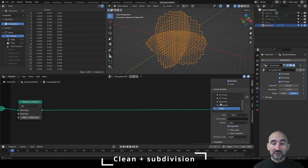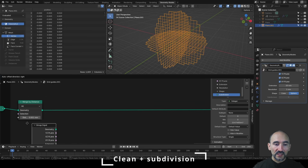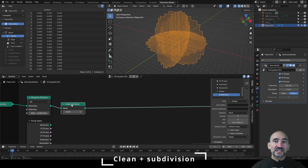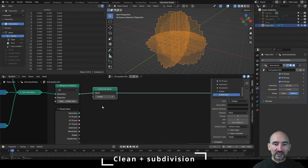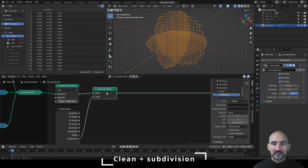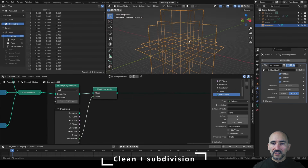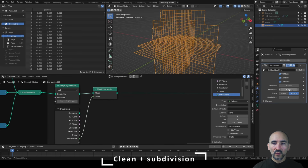Now we can add the other features, so the subdivision. We need to add another input parameter as an integer, and this is the subdivision from 0, and this is a single structure type, and we can add another group input here and add a subdivision mesh, not surface, because we don't want to smooth the surface but easily subdivide each face by 4 for each level of subdivision, and we can link this subdivision like this. This can be useful, for example, if I have a resolution of 4, you can use this subdivision to increase rapidly the number of subdivisions, so 4, 2, 1, and so on.